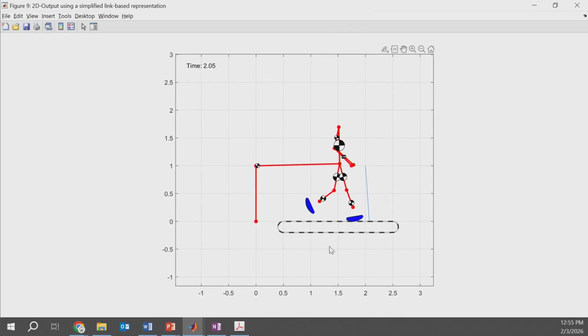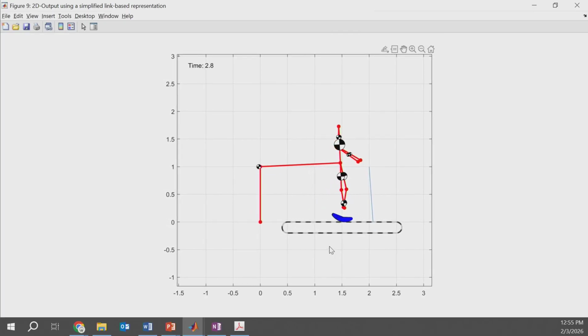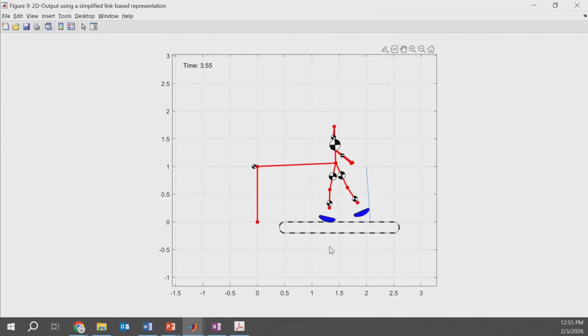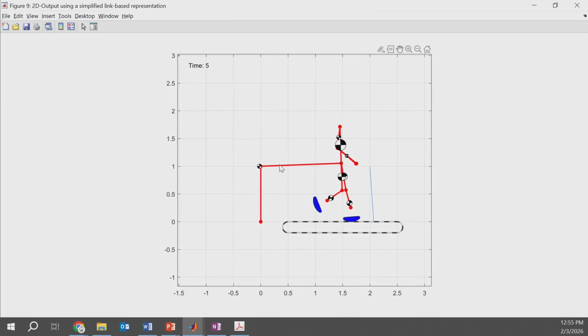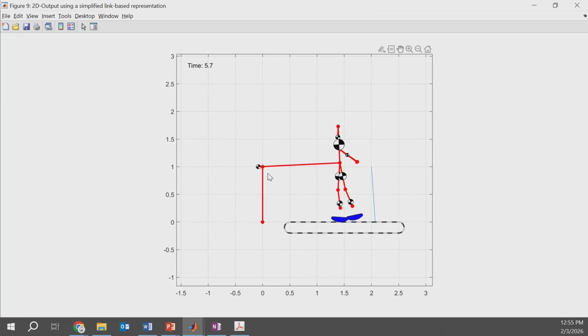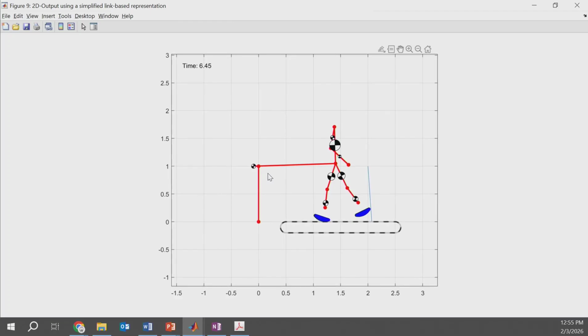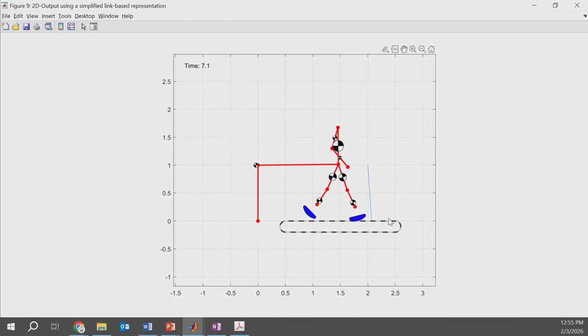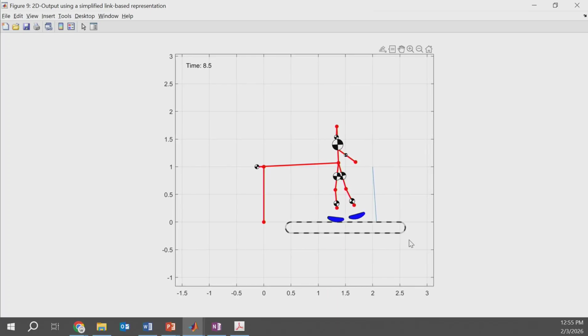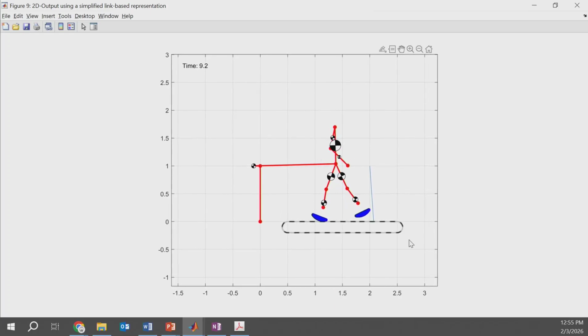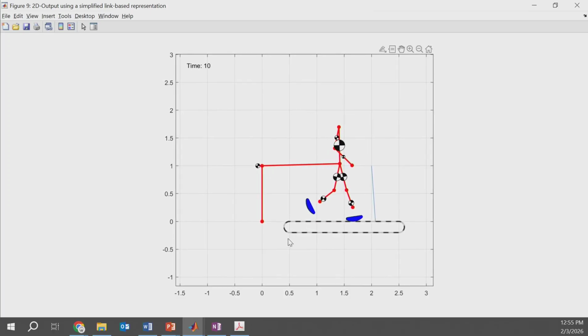And this is what we have. So what you see here is an animation based on the methods taught in this class of a system that has no motors. None of these joints are actuated. Here you see our virtual 3 degree of freedom joint, which in this case actually is going to be a physical 3 degree of freedom joint. Gravity is pointing a little bit to the right to drive this. And this is walking completely passively, right? So we're trying to build this.